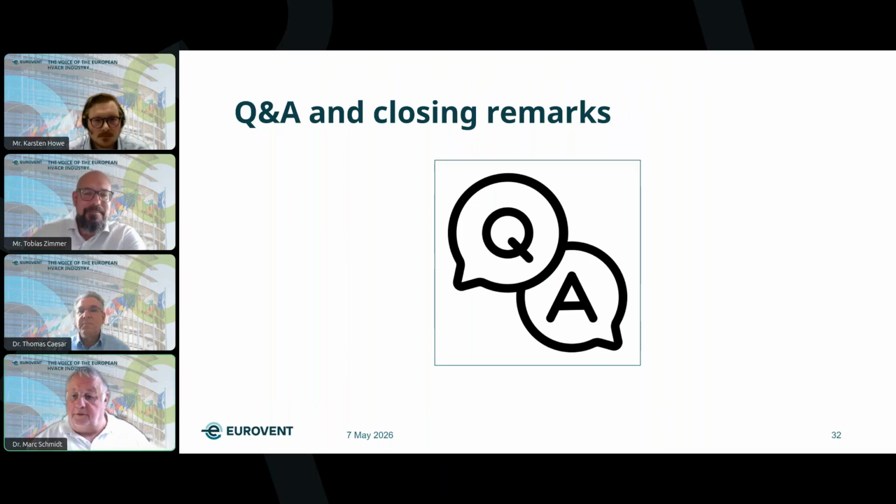Okay, thank you. And there is a question, what is the difference between molecular filter and HEPA filter by the explanation you gave by his performance? I can take this question. So we're talking about two completely different filtration things. On the one hand, for the HEPA filtration, we are talking about most of the time solid particles we are separating. So we are talking about particles like for H14, you have 99.995% of the solid particles which you filter or which don't come through.